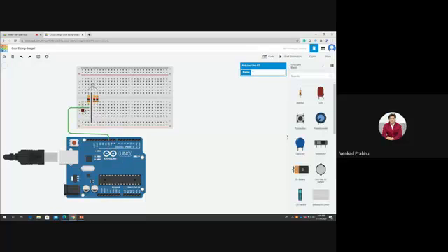Okay. This is for the red color. I have given it to the 10th pin, so change this into red color, and go to the blue color. Take it from any one pin slot, click it, and give it to pin number 9, and change this into blue color. For the last one, which is the green color, take it, click it, and give it to pin number 8. Let it be in green color. So 3 pins I have given for the 3 colors.